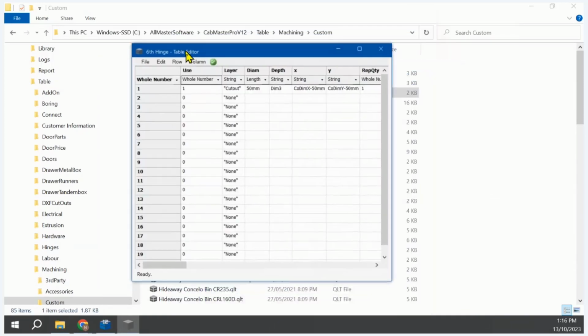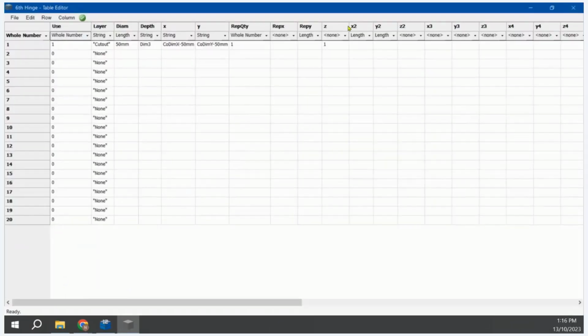This will always open on your main screen. So our hinge plate is going to be 2 8mm holes spaced 32 millimeters apart and set back from the front edge of our end 37 millimeters. We're going to base this on the Bloom hinge pattern,